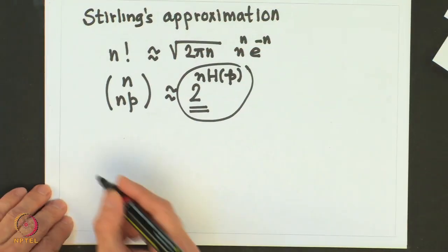But if we decide to use only a subset of the possible sequences and select this subset in such a manner that the set of highly probable received sequences for each element in this subset is non-overlapping, then reliable communication is possible. Okay? So, if we can do this, then let us see what happens.